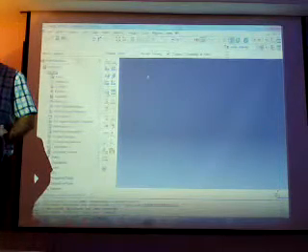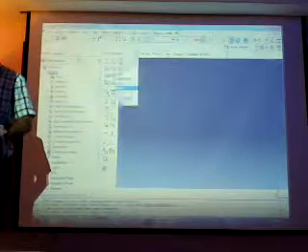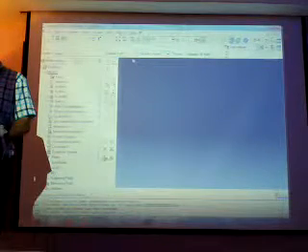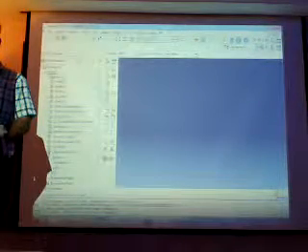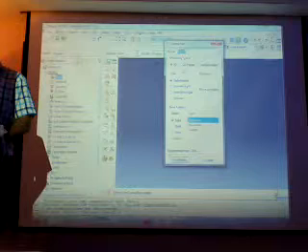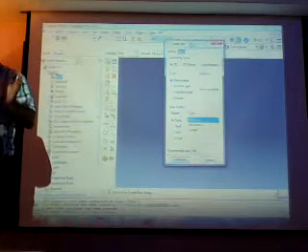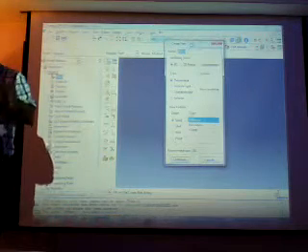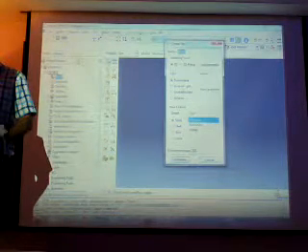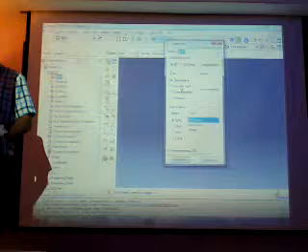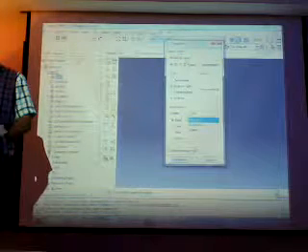Okay. Just choose a very simple die. Okay, first we are going to part and create our die. As you know, our die is undeformable. Actually it is deformed, but we assume here it is undeformable. So we take discrete rigid as a die.